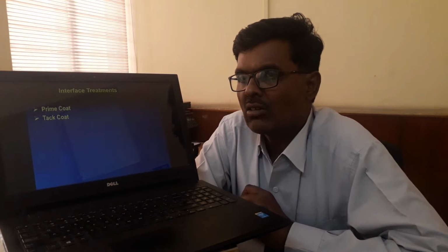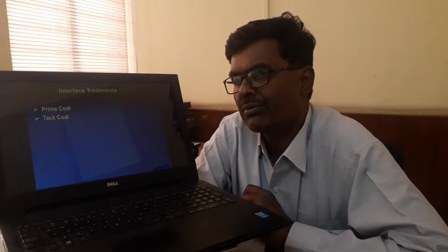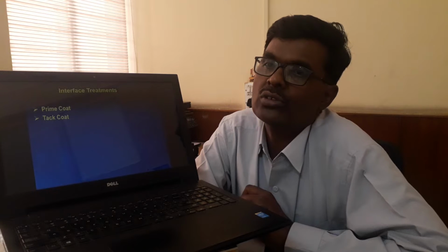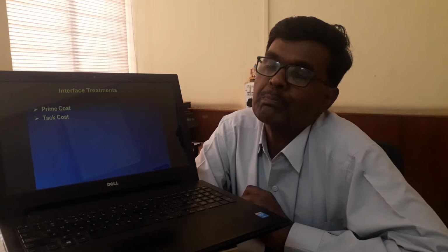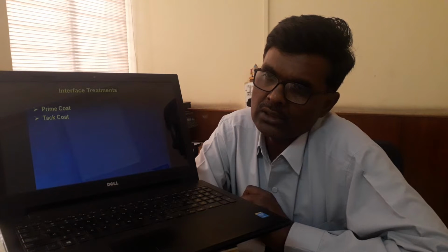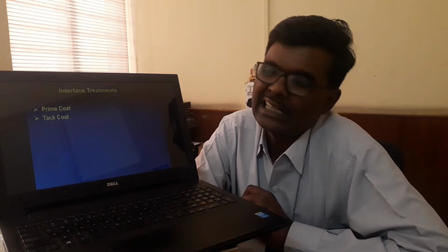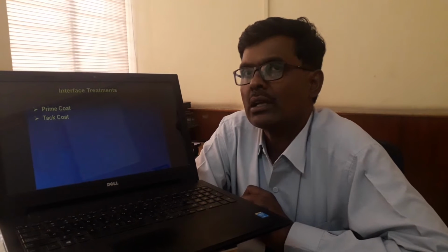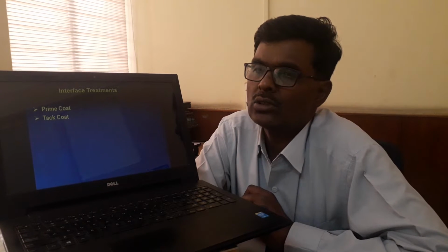And then if there is a requirement of profile correction course, when the profile of the receiving layer is not proper, then you should go for profile correction course. Wherever this profile correction course is not more than 40 mm, then this layer is constructed as part of your proposed or designed overlay. Wherever it exceeds 40 mm, the profile correction course should be constructed as an exclusive layer.